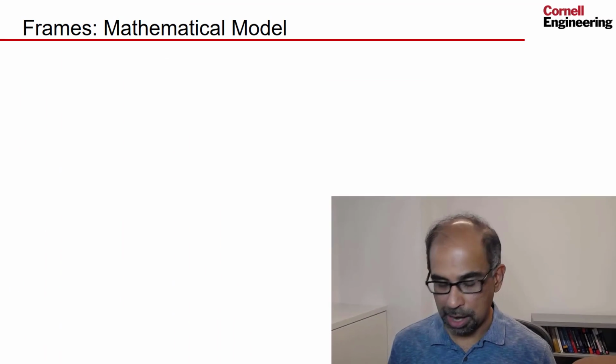In trusses, because you have only axial elongation or contraction, the cross section moves in the axial direction along the midline. In beams, where you have only transverse loads, the cross section can move in the transverse direction, up or down, and it can rotate. So you're making assumptions of what the cross section can do. And in the frames, the cross section can have axial as well as transverse displacement, and then it can also rotate. Let's take a look at how this works out.